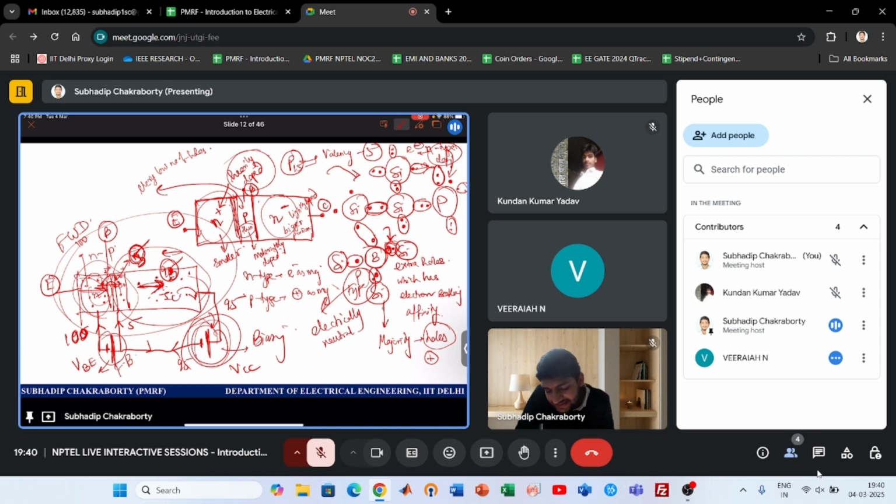But due to the reverse bias, there is some leakage current due to the flow of minority carriers, a small reverse leakage current. But that is very low, and the actual current is in the collector from this emitter junction, which was highly doped.